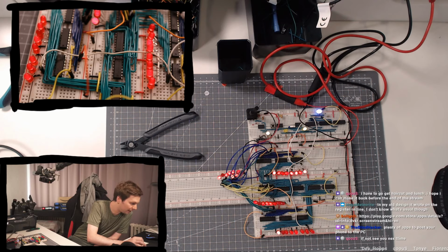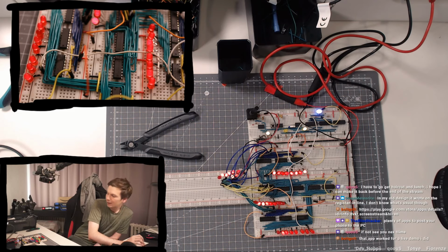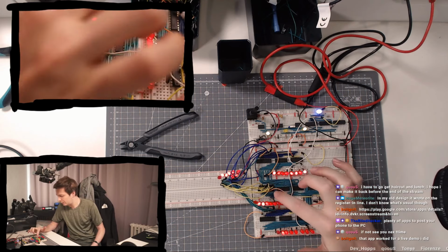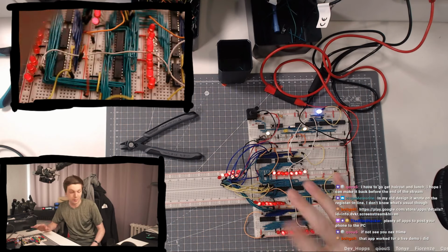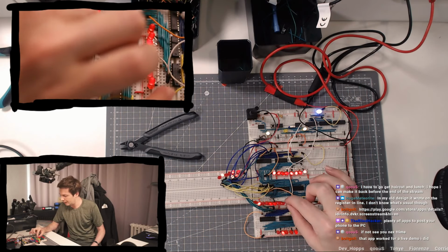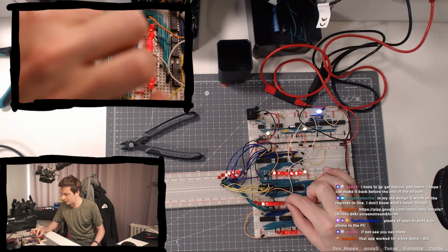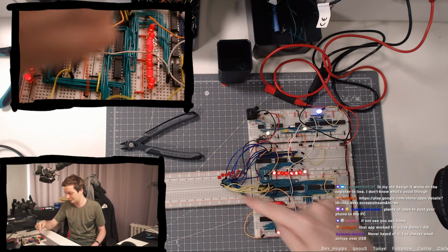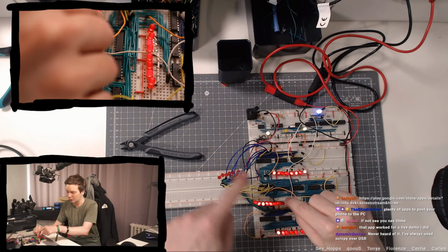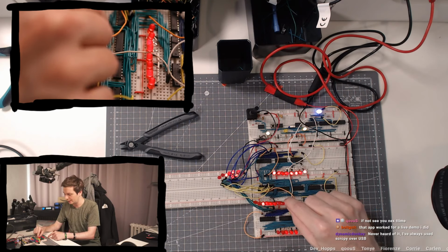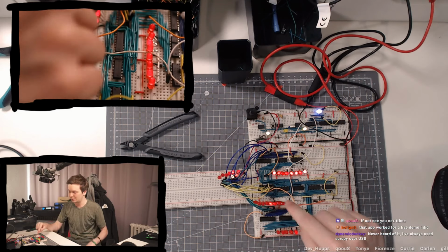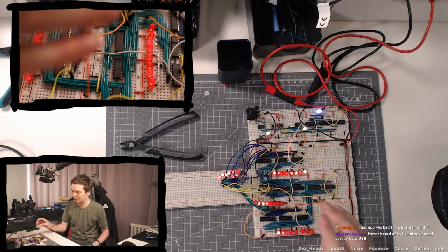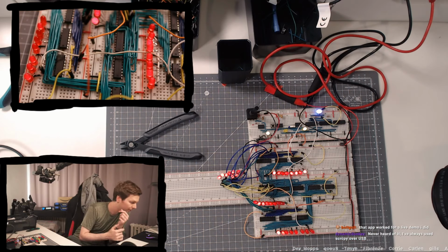Does the ALU write directly to the main bus in this design? Yes, but we can enable or disable this. This cable here is the output enable. So if we disable that, now it's also stopping because the value is not being put onto the bus, which this is reading again. So with this we can enable or disable the ALU to write to the bus or not.